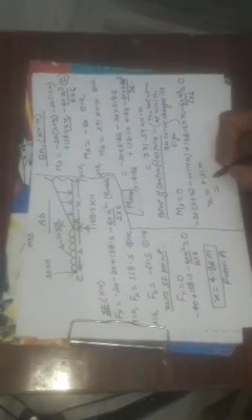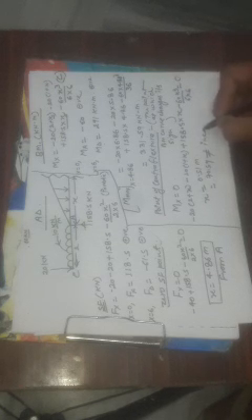0.5 into x minus 60x cube upon 6 into 6 equal to 0. Solve this equation, then we will find the value. There will be 2 values for this expression, and these 2 values are x equal to 0.51 meter, and second will be 70.59 meter. So this is an incorrect value, because the value must be less than 6, right?